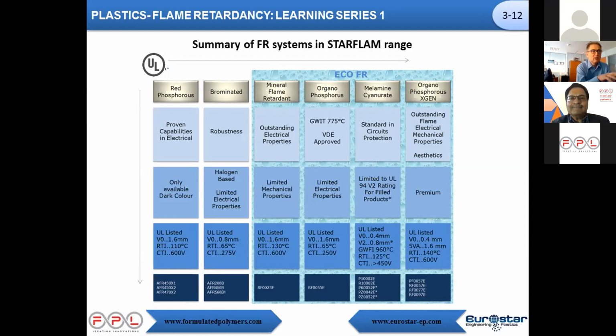Mainly it is to explain that there is no perfect flame retardant system. It's always a matter of compromise. It can be a compromise for cost, but most of the time it is a compromise for performance. And what is true in one business, for example electrical vehicles, will not be true if you are making a contactor, an MCB, or some train seats. Because basically the goal is always the same: to stop the fire or to prevent the fire from occurring.